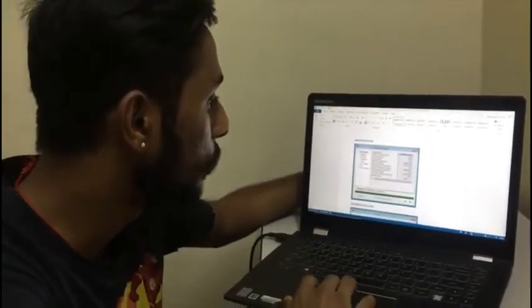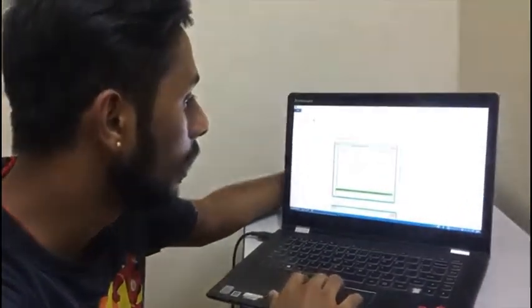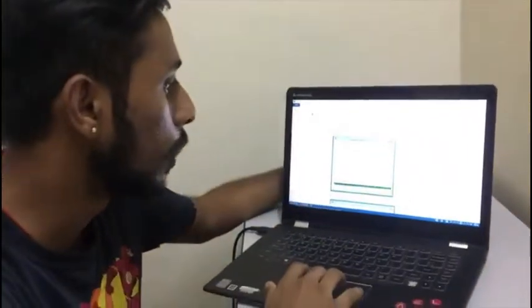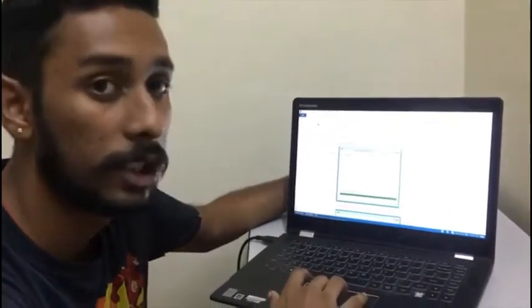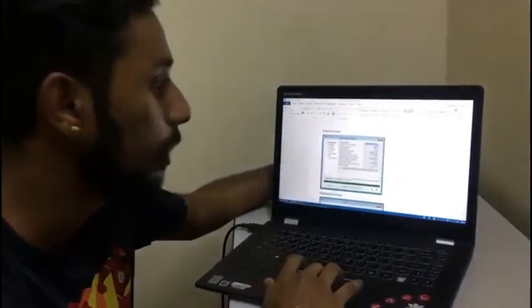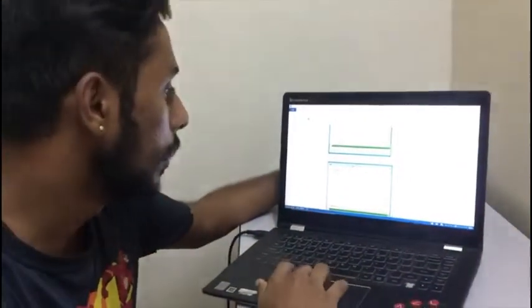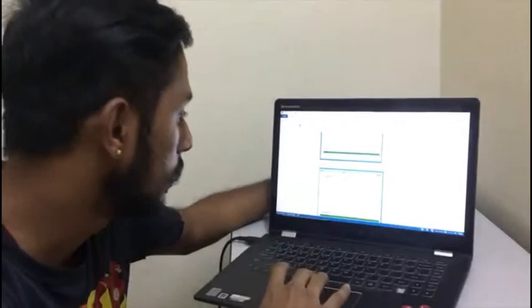Coming down to the superheated steam's property table, we have a vapor phase fraction of 1, a temperature of 800 degrees Celsius, and a pressure of 1.7 bar. Coming down to the distillation feed stream, we have a temperature of 10 degrees Celsius, a pressure recorded at 1.52 bar, and a flow of 1060 kg per hour.